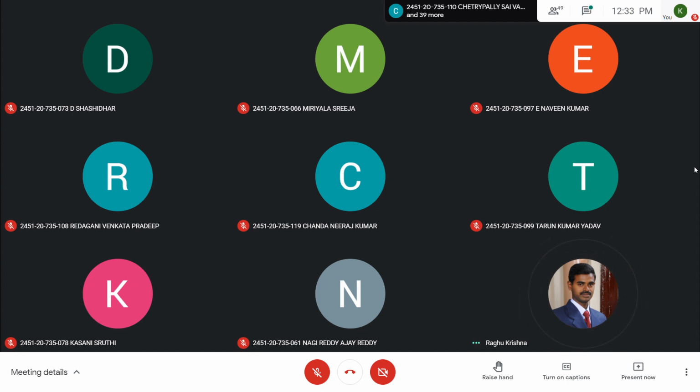KCL here. Applied KCL at this node. V minus 15 by 6 is outgoing current. V by 3 is outgoing current. Minus 6 amperes because incoming current. And V by 4 is outgoing current. So solve the equation and get the value of V. So what is the value of V you got?